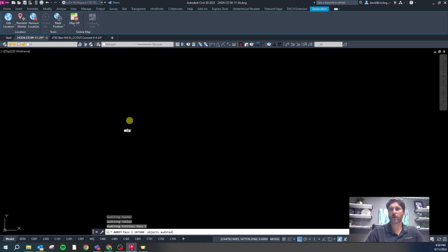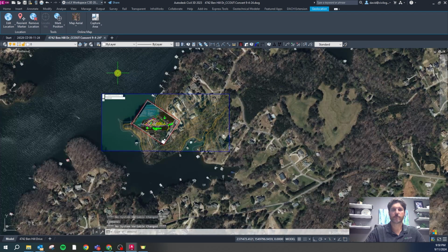This is the template drawing. I don't expect there to be any errors, but there are, so now I know I need to go back into that template file and make a repair, do an audit. Okay, it fixed 8 errors. Let's save that again. Let's go back to this guy. Purge end, audit, fix, yes. No errors. Save.